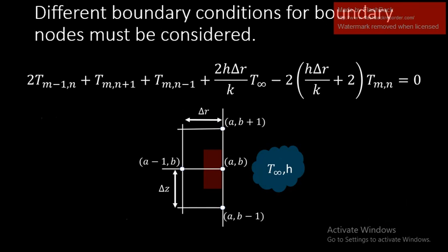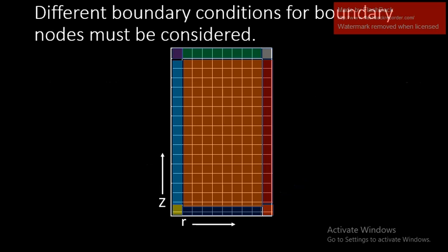If the nodes are not existent next to it, you have to apply boundary conditions. These boundary conditions come from the initial energy balance, but it simplified down to this one, for example, where you have an exterior node facing external convection. We basically had to separate out each and every location, so the four corners were individual nodes. And then each one of the sides had their own equations because of the type of node that they were and the boundary condition that was applicable.